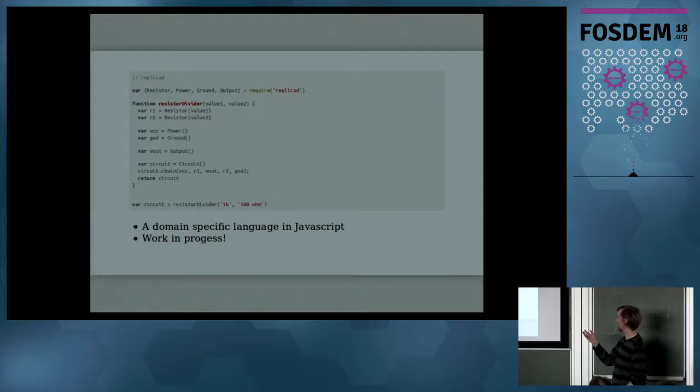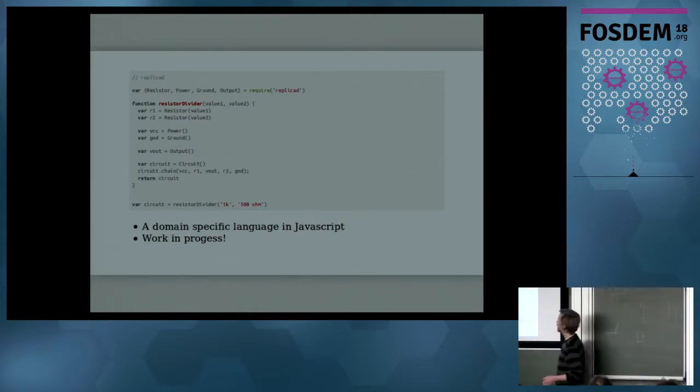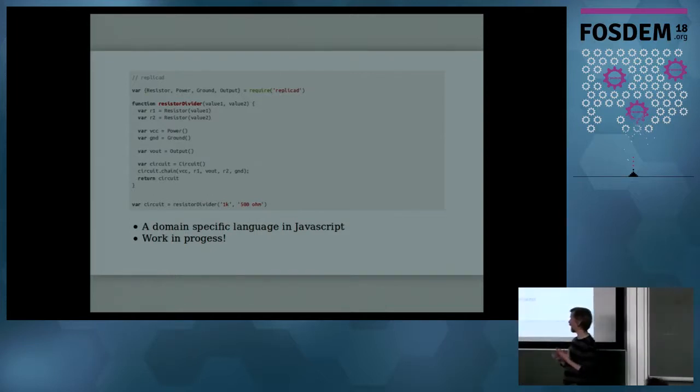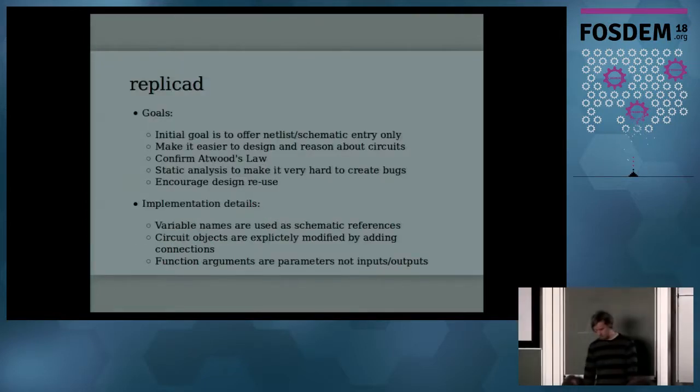So the way I've played around with doing this is to use JavaScript language transforms, which then, when you say my resistor is R1, and you just give it the value of the resistor, then in your schematic or in your output, really, R1 will be that resistor. So I'm using these language macros or processing to get that done.